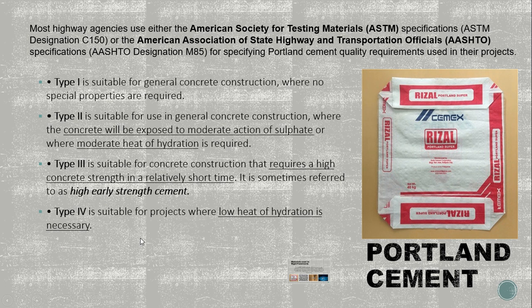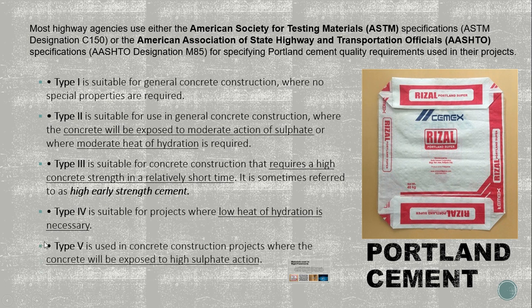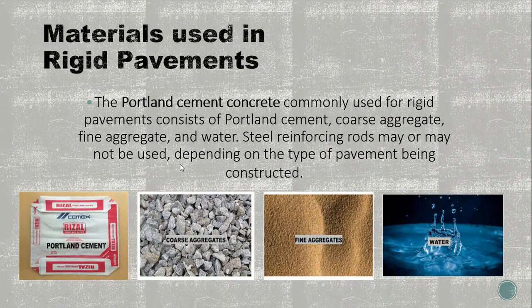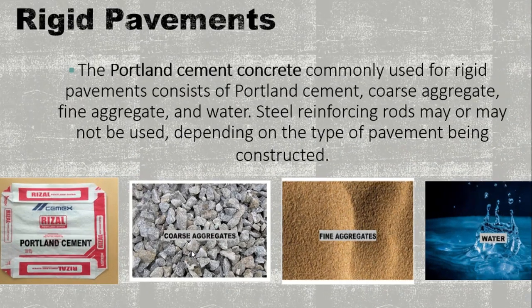Type 4 is suitable for projects where low heat of hydration is necessary. And lastly, Type 5. It is used in concrete construction projects where the concrete will be exposed to high sulfate action. Another material is the coarse aggregates.